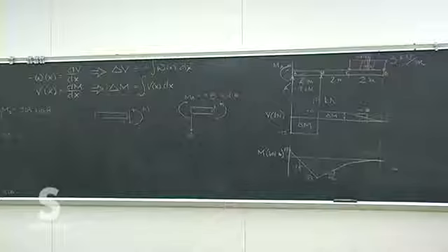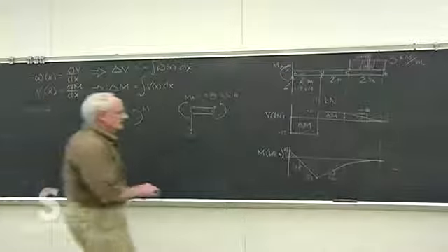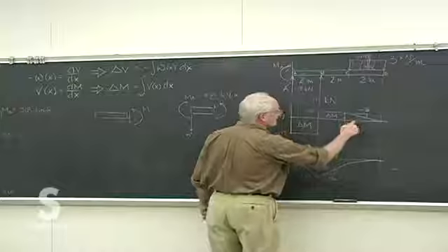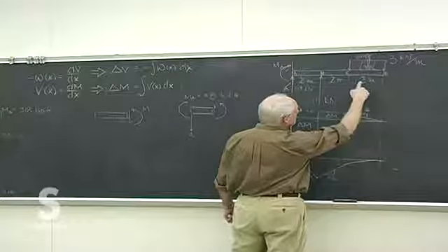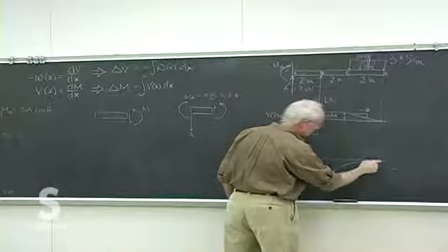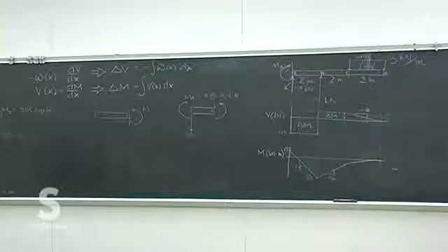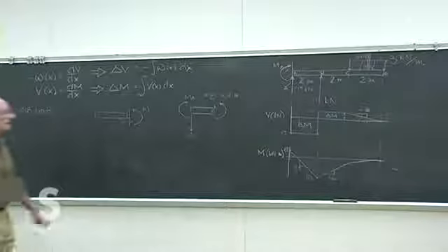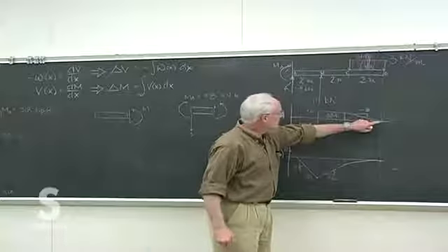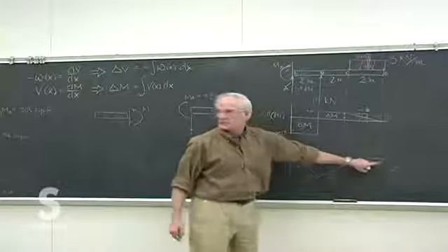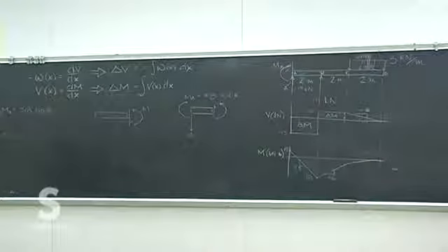You can bring it into 0 and you've got the whole curve. And all of the stuff agrees there. The area of that should be -6, and indeed it is, or +6, because that's the change in M that we see there. All the slopes agree. Shear goes to 0, so the slope of the moment curve goes to 0. And we're done.